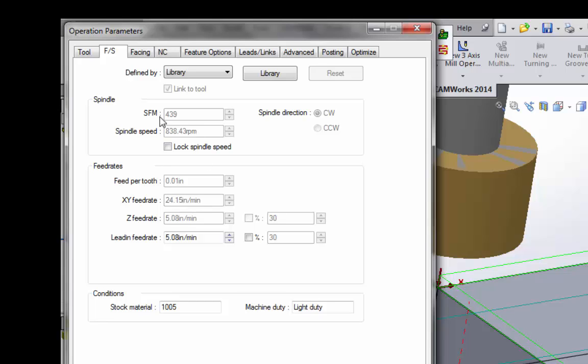Ultimately, for these calculations there's many calculators, there's an internal library, but what I find is best is to always find somebody who is running the machine shop and verify with them that you are cutting at appropriate speeds by simply asking them what is an appropriate spindle speed and feed rate for any given cutting application.